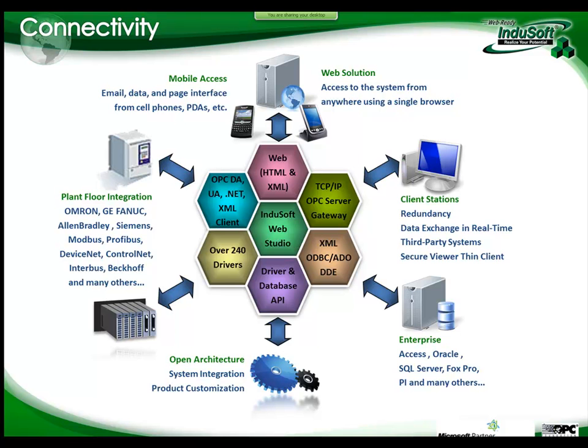So on this chart here, I'm going to start talking about this one here on the bottom. InduSoft Web Studio offers you about 240 different communication drivers, speaking several different protocols as part of the product. So if in your plant you're running a PLC that speaks Modbus for the control part, InduSoft has native Modbus drivers for all the different Modbus flavors: RTU, ASCII, serial, Ethernet, Modbus Plus as part of the product.